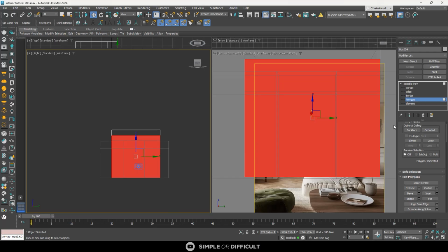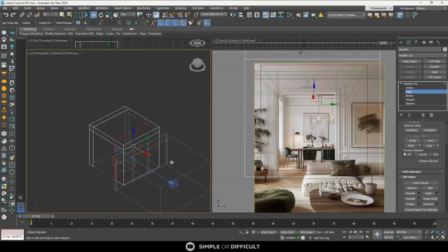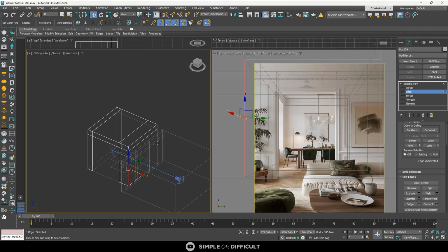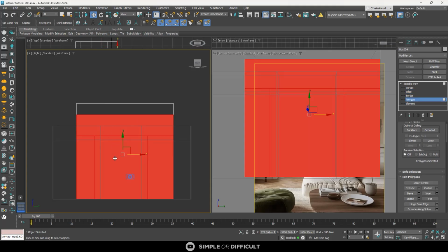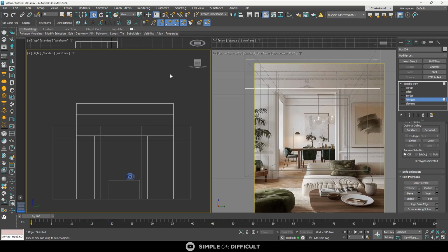I want to do it in such a way that, hold on a minute. I'm going to create, between these two edges, I'm going to use the connect tool to create another edge there. Then raise it up. Then with this now, I can create two edges. So move this one into this place. Hold down Alt, deselect it, and then move this other one to this place. Now I want to create this same opening that we are having here in there.